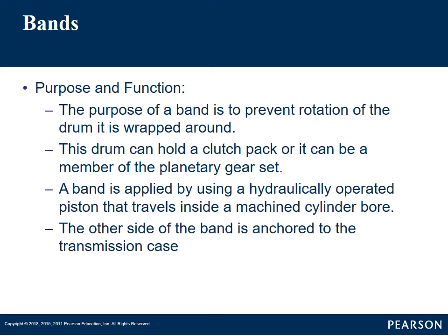This band is applied hydraulically by using a servo piston that travels in a machined bore. We talked a little bit about this when we were talking about accumulators, how that softens the apply to these servos. And we'll talk a little bit about how these servos work here in a minute. And then the other side of the band is anchored to the transmission case.